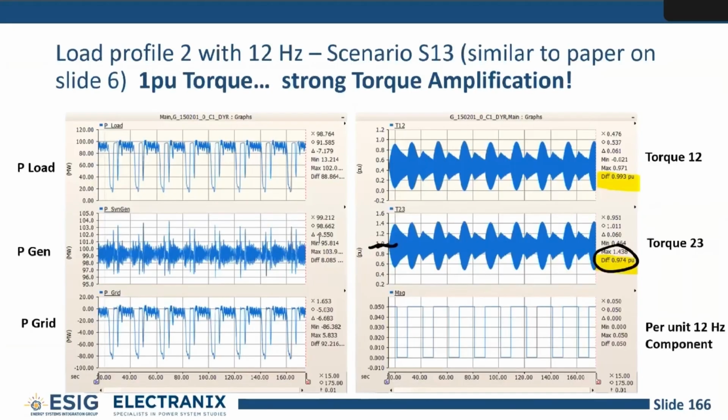So if you're dropping off and the voltage really moves, basically if your system is having trouble because of VAR adequacy or some of these other problems we've had, very high voltages, for example, if you reject the load and you get an overvoltage transient, we could definitely cause ride-through problems for renewable plants. But the steady state variation, I'm trying to imagine ways that could realistically cause a problem for an IBR plant. And I think it's unlikely. It's possible. But if the voltage is moving a little bit, a wind farm isn't going to mind that, as long as it's not weirdly driving some controller mode or something like that. It seems unlikely that it will be a problem.